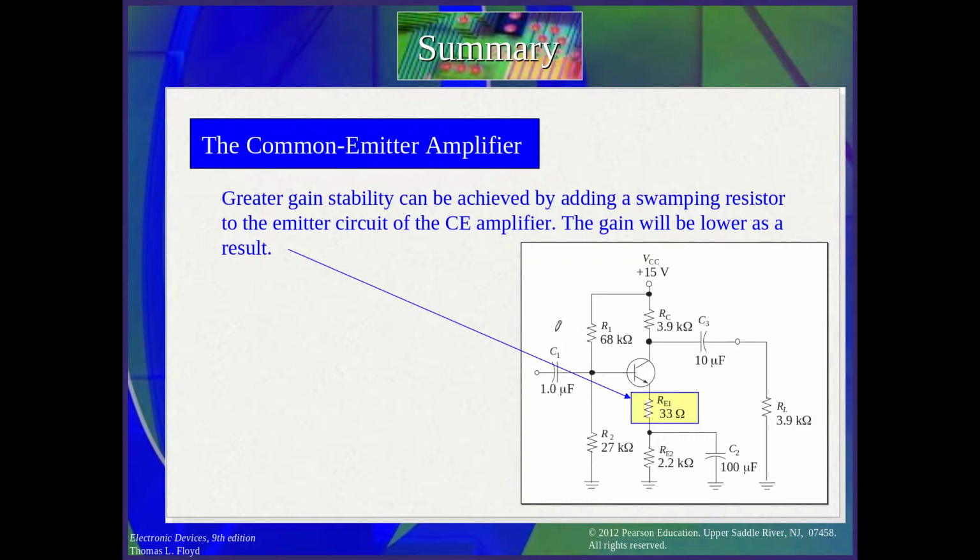No, there are changes that may happen to the circuit, or additions, or you remove something to gain something. So you have to understand and take into account that the calculation may change from one circuit to another. Okay, now they put here RE1, which is called the swamping resistor. He put it into the emitter circuit, so as to achieve more stability in the gain.